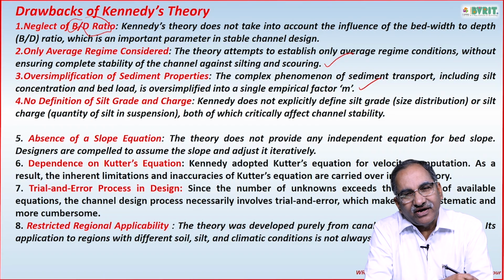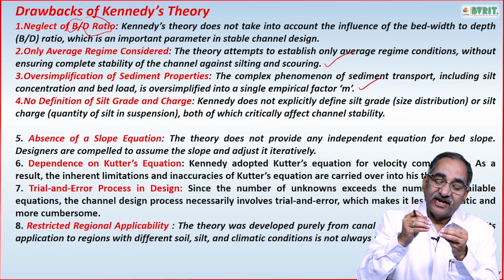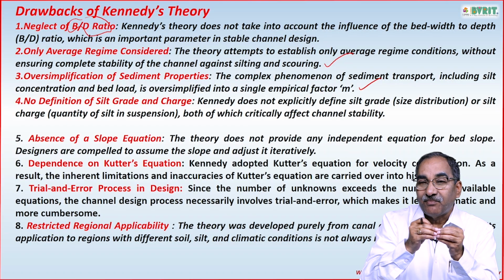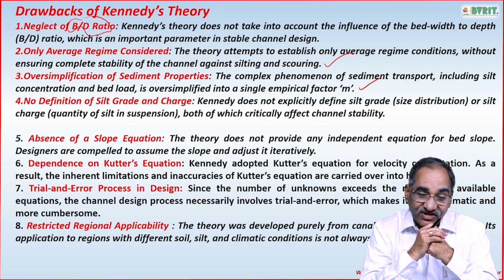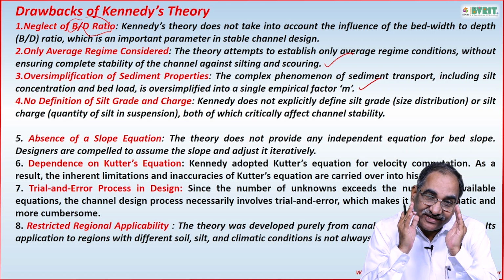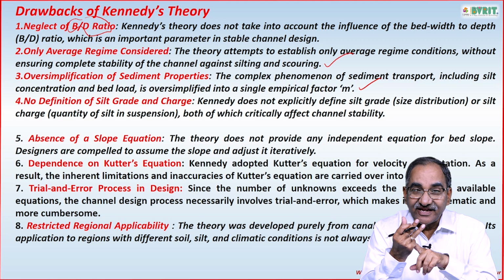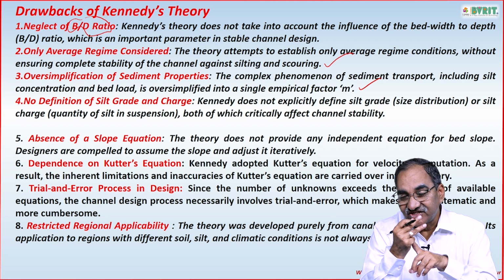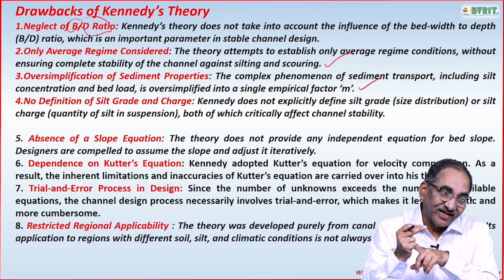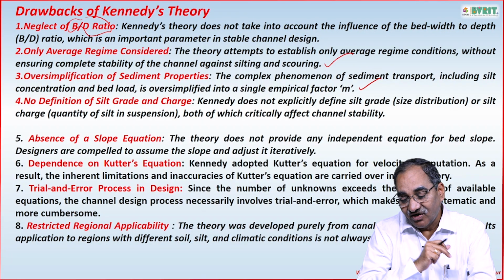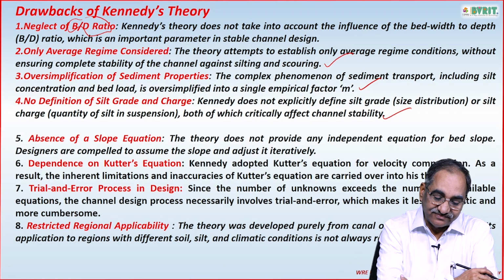Then he never talked about the gradation, that means the different gradations of the silt, the particle sizes of the silt. He did not talk anything about it. And the second thing is the quantity of the silt that is being carried in the channel. The quantity is what we call the silt charge. The gradation is what we call the silt grade. Both are not really explained by him. That is the fourth drawback.